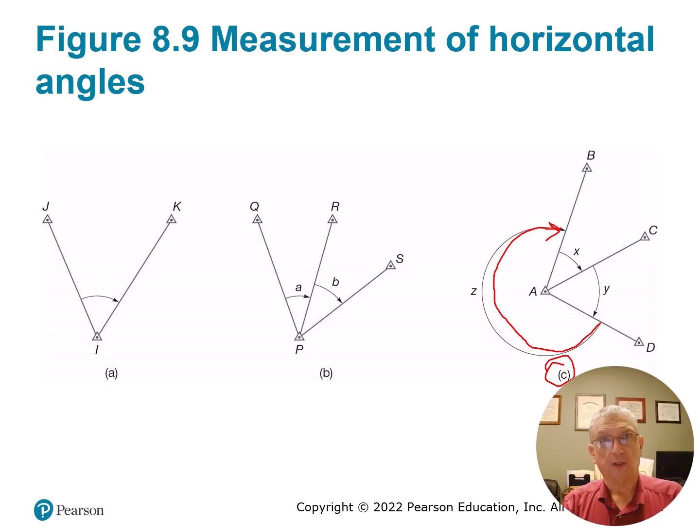It's just like with trig leveling, you take a direct and reverse on a foresight, because any instrumentational error is going to typically average out. If your direct is measuring a little bit low, then your reverse is probably measuring it equally high. And so the average of them is probably just dead on the money, or very close to dead on the money.